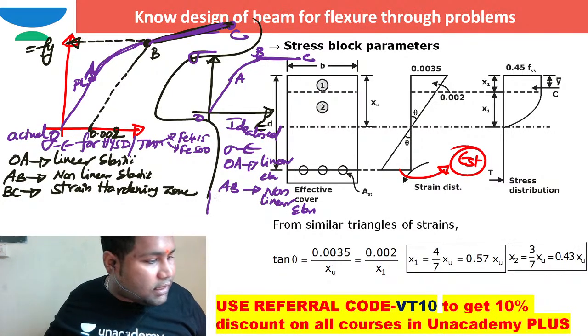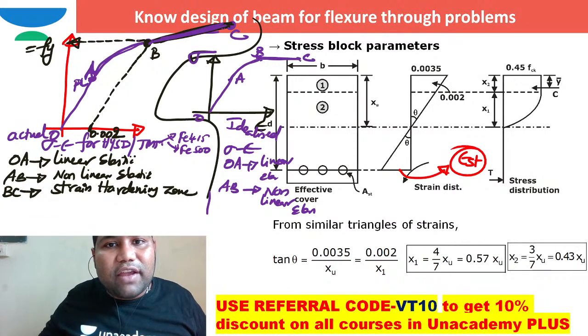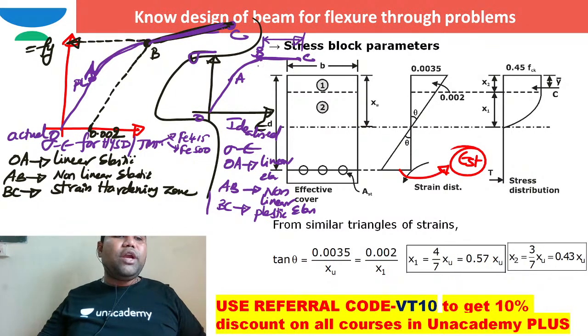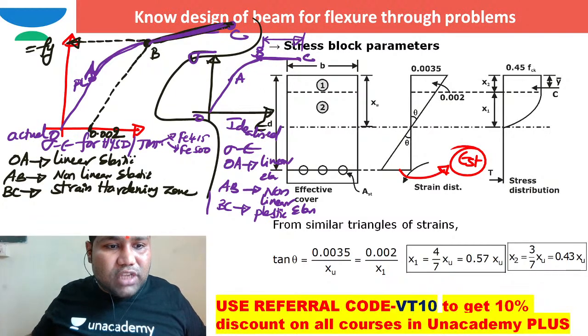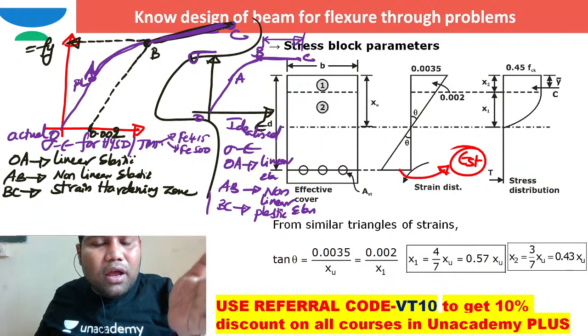And what is BC in this idealized stress strain curve? Can you see this BC? This BC is a plastic zone, right? So BC is treated as a plastic zone here. I am going to use this idealized stress strain curve. Some people will come and ask, sir, I don't want the idealized stress strain curve, I want the design stress strain curve for steel.